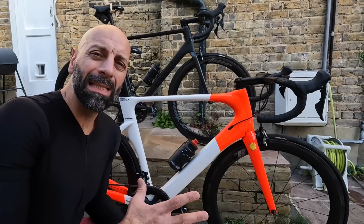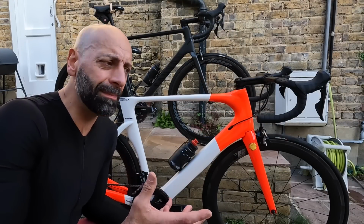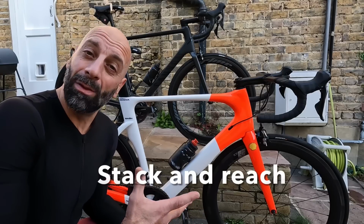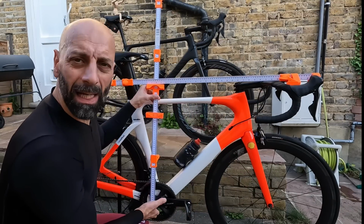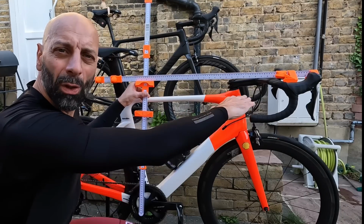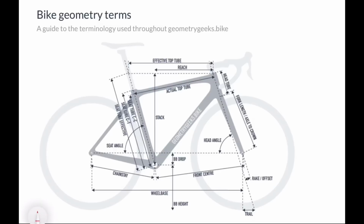Now, the top tube itself might not give you the full perception of how the bike is built, and two other good measures are the stack and reach. We'll show you the front end of the bike. So usually the stack is between the bottom bracket and the horizontal line of the head tube, so more or less this sizing, while the reach is from the perpendicular of the bottom bracket to the head tube.